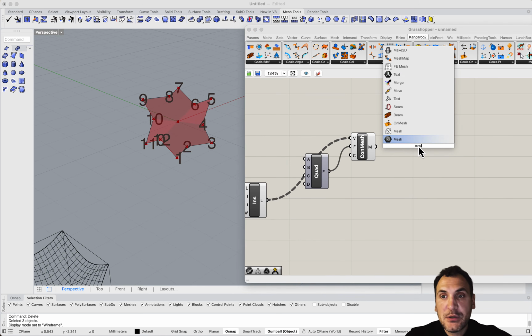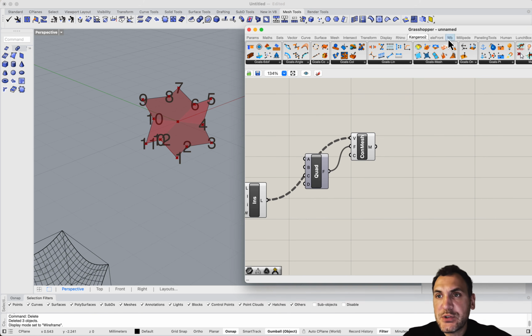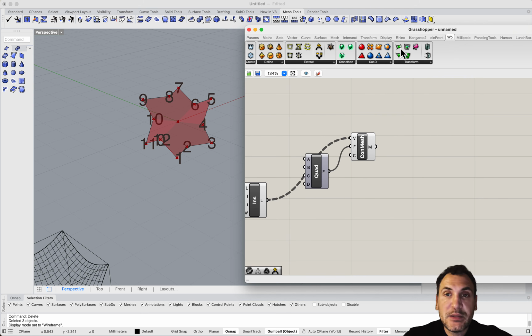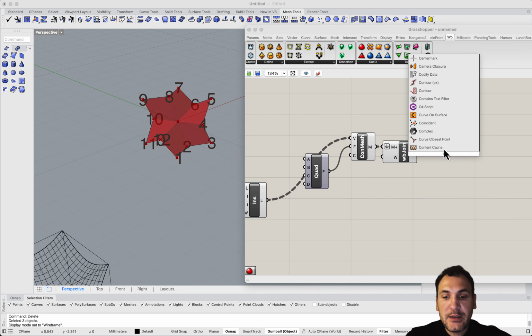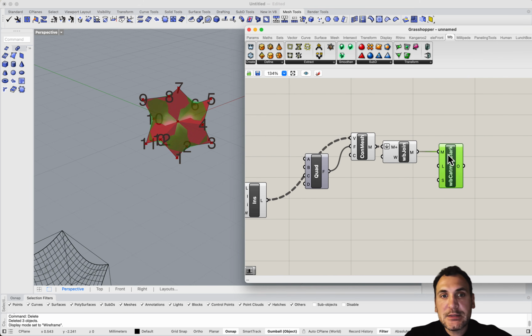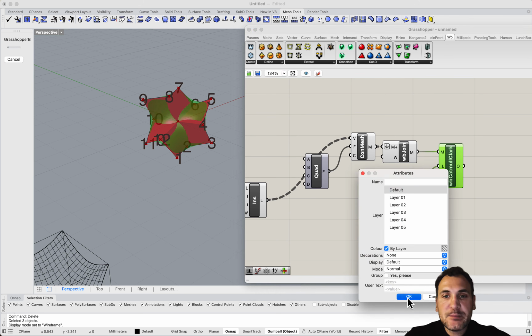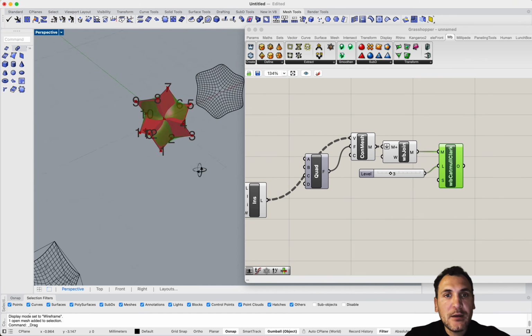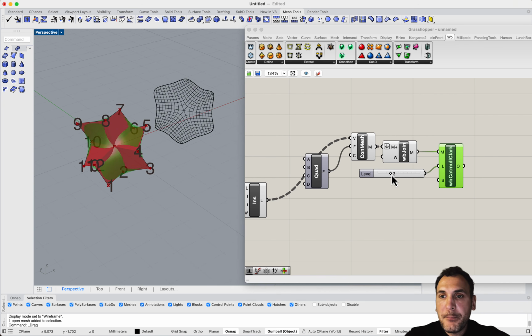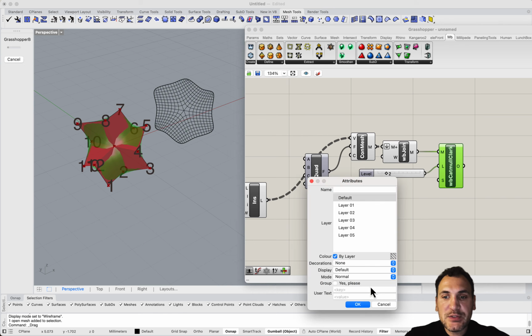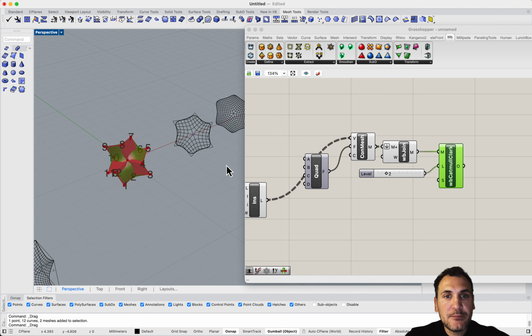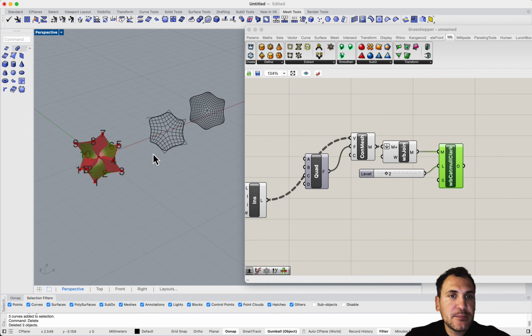So if you do mesh join, or we can look into Weaverbird function. You have to download this plugin. But if you go here, do join meshes and weld, so you can just flatten this list, and you can do Catmull-Clark, for instance, that will give us a smoothed out geometry. So if you bake this mesh, you can see that's kind of a third level. This is the second level, so I'll just plot these steps of segmentation or subdivision.